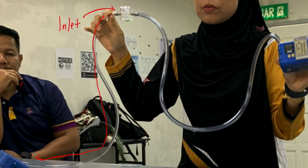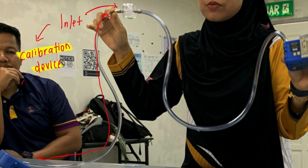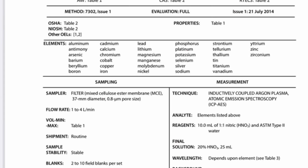Next, pre-calibration is carried out. The inlet of the calibration cassette is connected to the calibration device, while the outlet is connected to the air sampling pump. The pump is then switched on and adjusted until the flow rate is about 1.0 liter per minute. After calibration, the pump is turned off and the calibration cassette is removed. A new cassette is then attached for actual sampling.